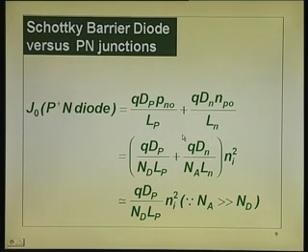To recall what we already know about p-n junction, I take a p plus n junction. Now, the total formula for this J naught of p-n junction diode is this. These are actually the carriers which are generated within one diffusion length on either side of the depletion layer, diffusing into that. So, when you substitute, this is the minority carrier concentration in the n type region, thermal equilibrium. This is the minority carrier electron concentration in the p type region, thermal equilibrium.